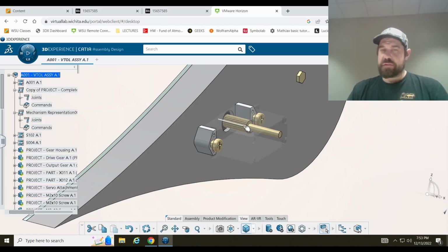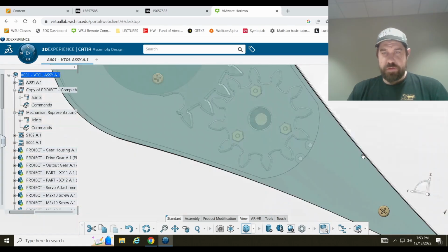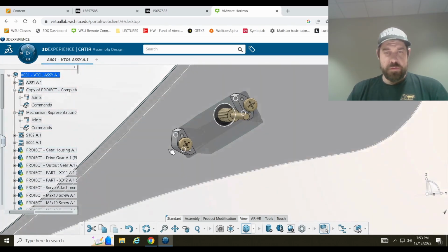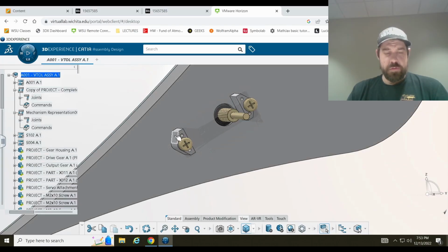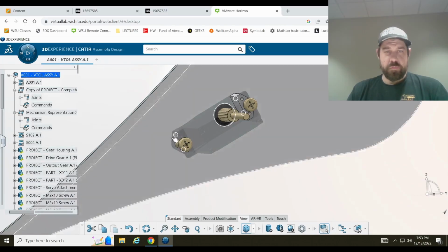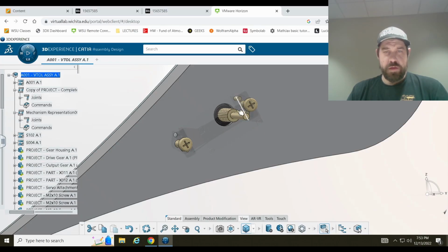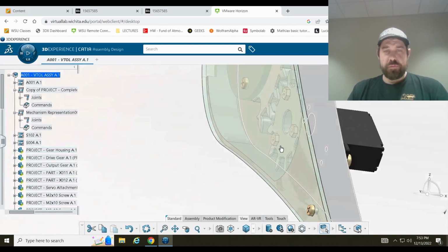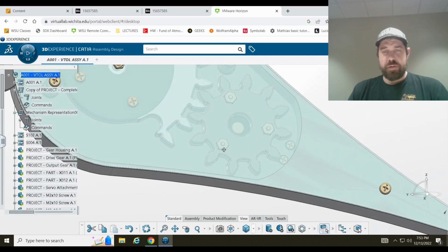I needed to keep this aligned with the rest of this assembly so that this gear would stay aligned. So these mounting lugs I created to attach on the back with pretty tight tolerances on their location so that they align this servo motor shaft directly in the middle of this pass-through. That pass-through gets us to the drive gear.